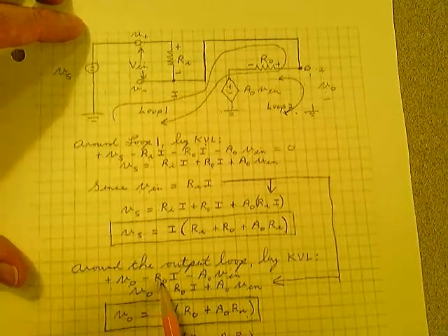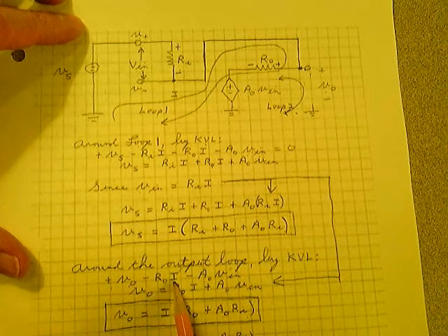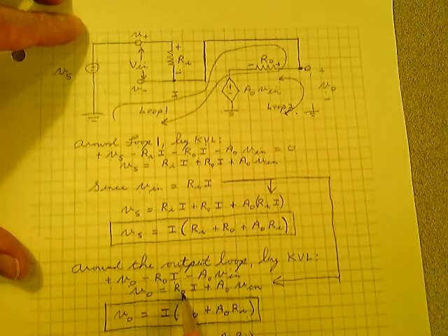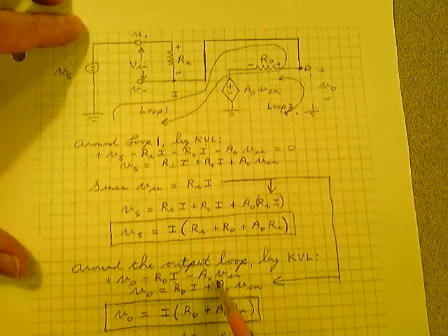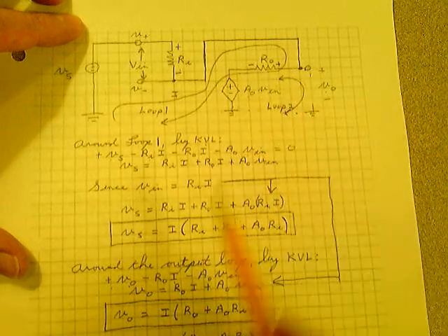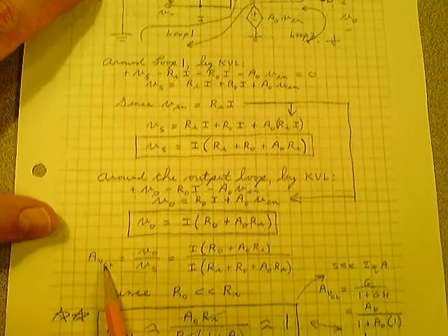Minus R0. Then you stop and think. What current? I. Just our loop analysis. That's the only current that goes through there is I. Okay? And then you look, you have a minus V out, V in right here. Then you're back to this point again. That's it. Clean that up. You get what V out is. You form the ratio. That's what this is all about.